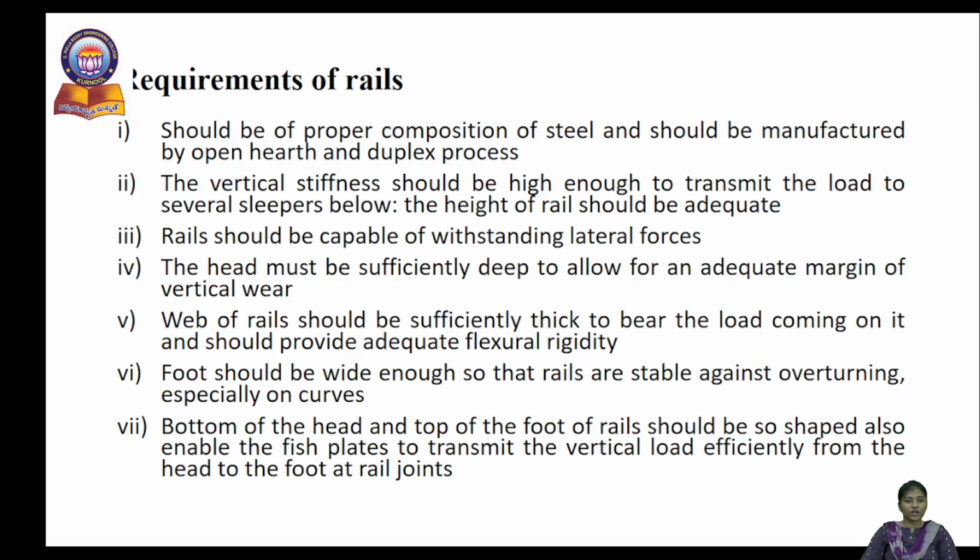It must be capable of withstanding the lateral forces. The head must be sufficiently deep to allow an adequate margin of vertical wear. The web must be sufficiently thick in order to take the loads which are coming laterally. The foot must be sufficiently wide. If the foot is not wide, then overturning will happen, especially on horizontal curves.